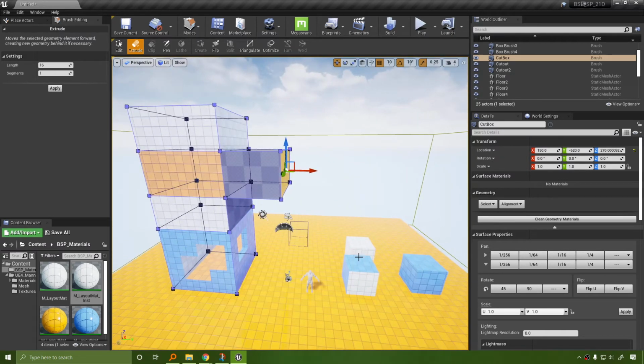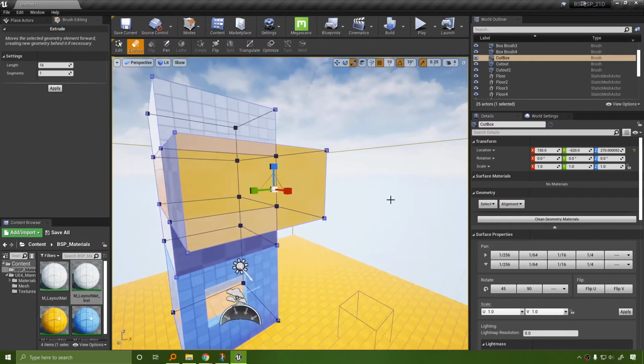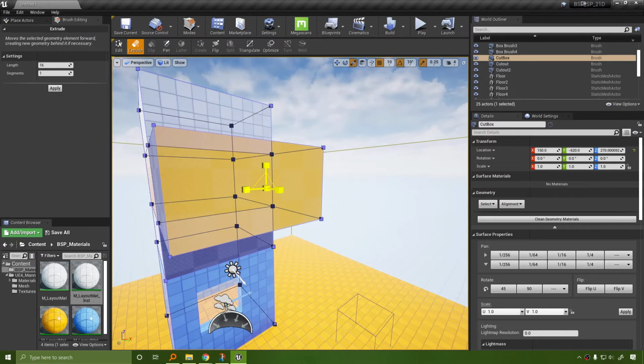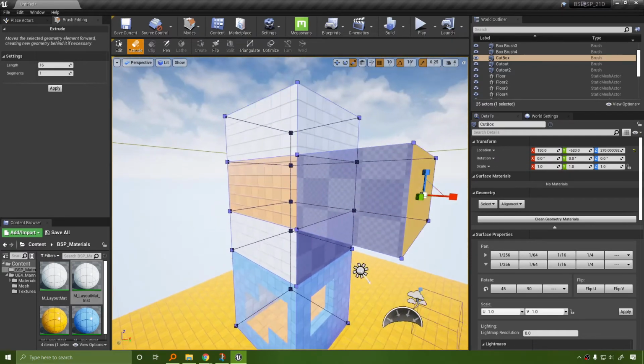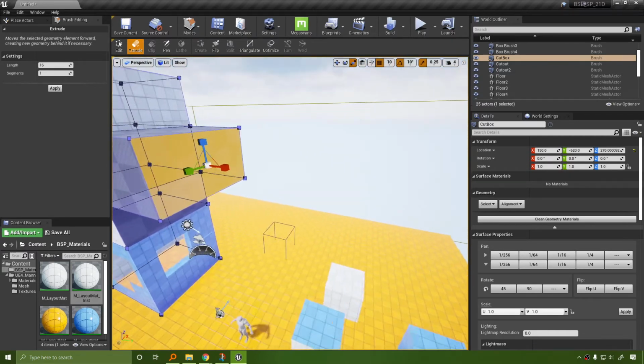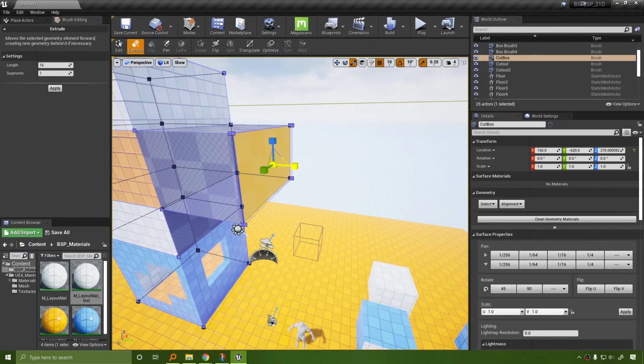And we can make some semi-complex shapes using this method. Be very careful, because at this point, imagine trying to scale something that has non-consistent deformer scale, right? We can set up and see if I can get this to work. Sometimes it'll let us, sometimes it won't. As you can see, it won't let me. You can't scale an extrusion.